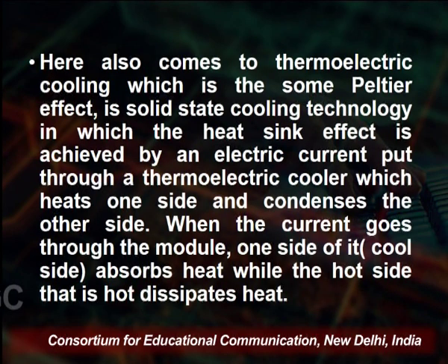Thermoelectric cooling is based on the Peltier effect, and it is a solid state cooling technology in which the heat sink effect is achieved by an electric current put through a thermoelectric cooler, which heats one side and cools the other side. When the current goes through the module, one side, the cool side, absorbs the heat, while the other, the hot side, dissipates heat.